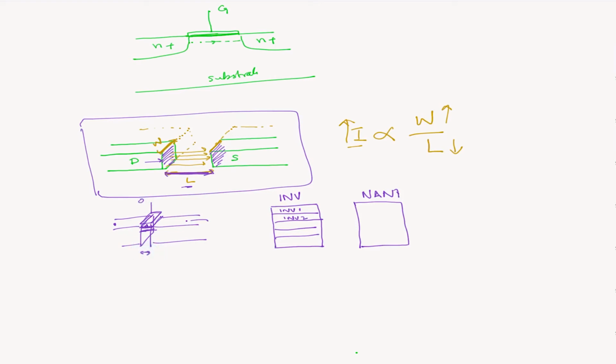But as we made this length smaller, it became very difficult to make this transistor off, so that even when you have 0 or close to 0, you still have some electrons escaping. And we started making our silicon dioxide thickness smaller, smaller and smaller. Eventually, we were really limited by the number of atoms in the silicon dioxide. So it was not possible to do more engineering of the silicon dioxide and still make it more controllable through this top structure.